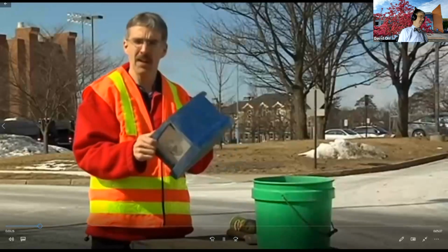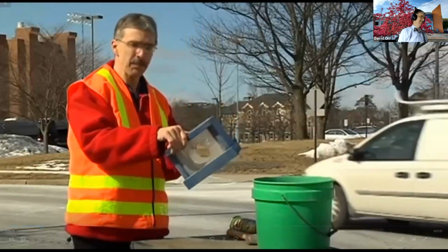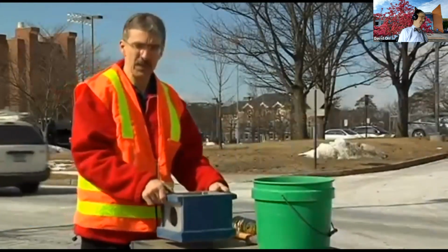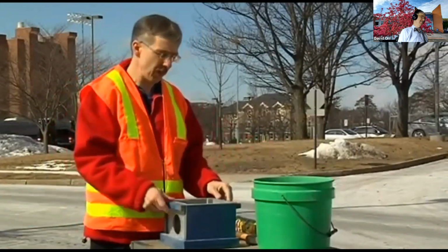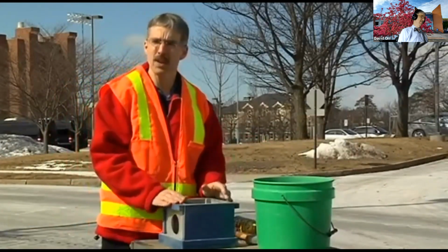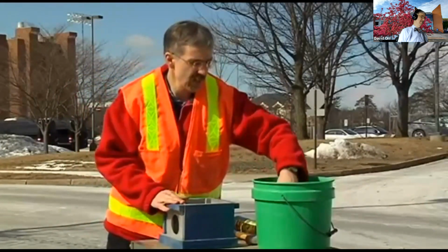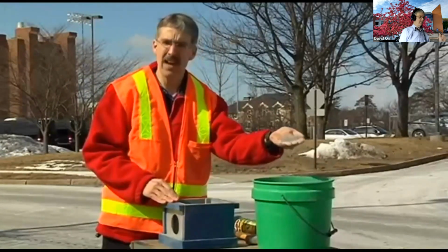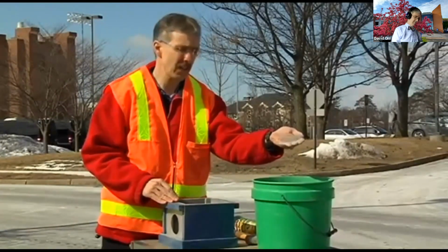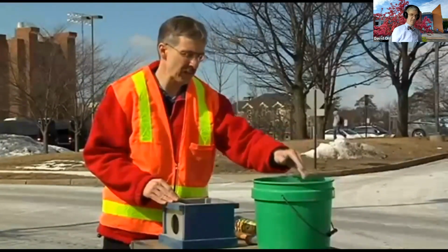We're going to be installing in our trench box here, which has some plastic on the ends just so we can see what's going on, but normally it would be open on both ends. First thing we need to do is put a little gravel in to bed the pipe, and it needs to have the right amount of moisture in it. It needs to be non-frost susceptible. This is obviously too dry. It doesn't have any moisture in it at all, so we need to add some moisture.